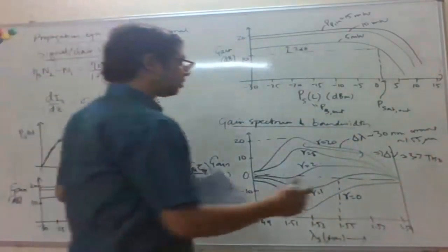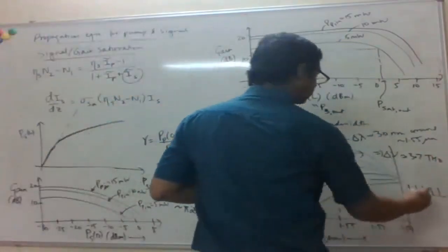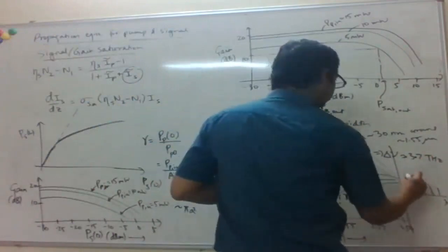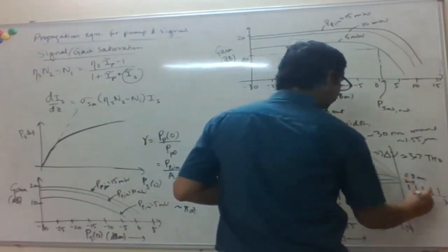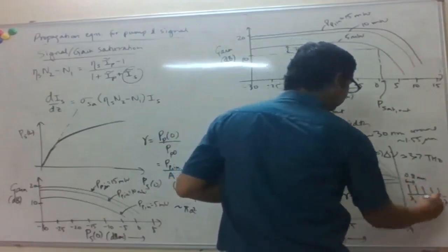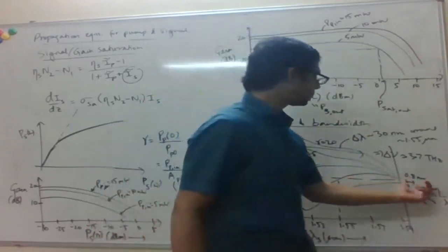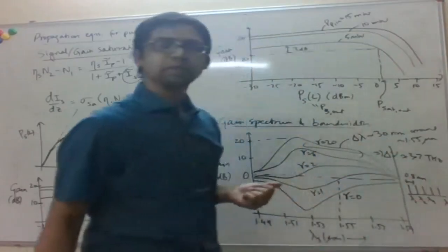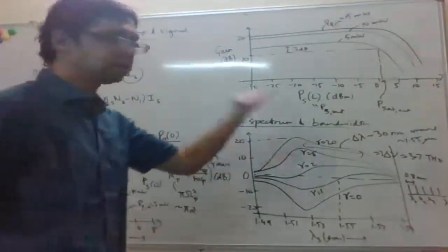Okay. So for example, now if you have a WDM grid, usually the wavelengths are spaced at a particular spacing. Typically, for example, for dense WDM systems, the wavelength spacing of different channels is about 0.8 nanometer. Right, so you can see that I can have, for example, 40 wavelengths within this 30 nanometer. So I can simultaneously amplify 40 channels.